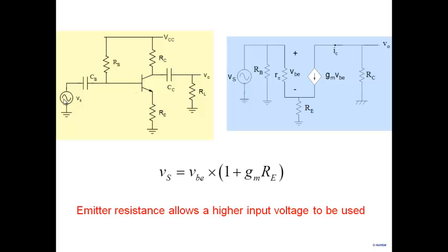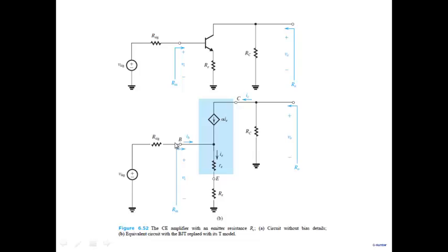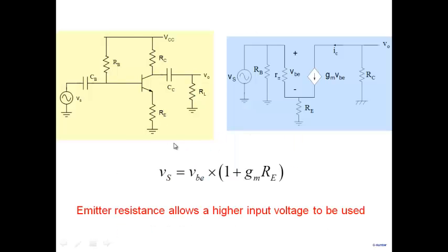If you have a 100 millivolt signal here, and you want 10 to appear here, you can easily calculate, I need a factor of 9 here, and how much resistance do I need to put here? Then you'll be able to apply a 100 millivolt signal here, and amplify that 100 millivolt signal with the similar one. Except that there is a little bit more to it, okay?